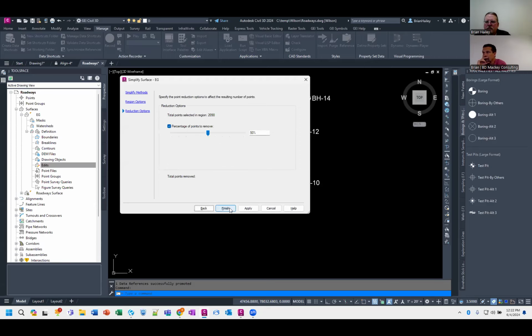But when you do this, you can say, hey, I want to remove this many points. So if you had 48 million points and you want to get it down to 900,000 points, you would just take 48 million divided by 900,000, and that's the percentage you want to get rid of, right? So you would do the math, and it turns out to be like 99.58 or something like that percent of the points. And then it'll do its best to remove those.